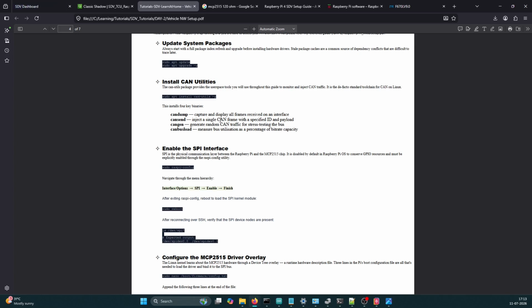You will connect through SPI, right? But by default, this Raspberry Pi has the SPI interface disabled. So what exactly we have to do is enable the SPI interface. You have to run this command: sudo raspi-config. Once you run this command, it will open the interfaces.